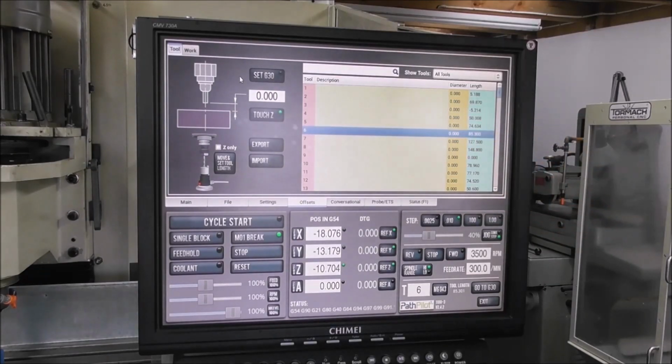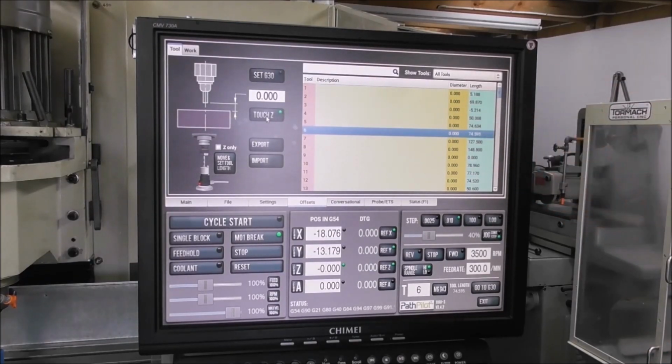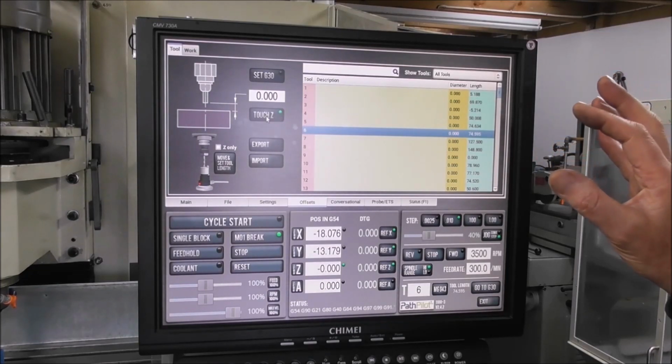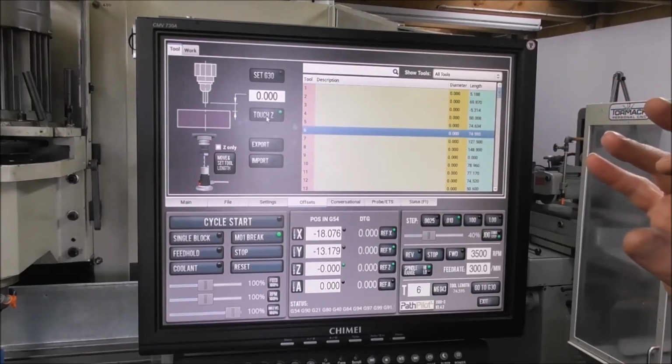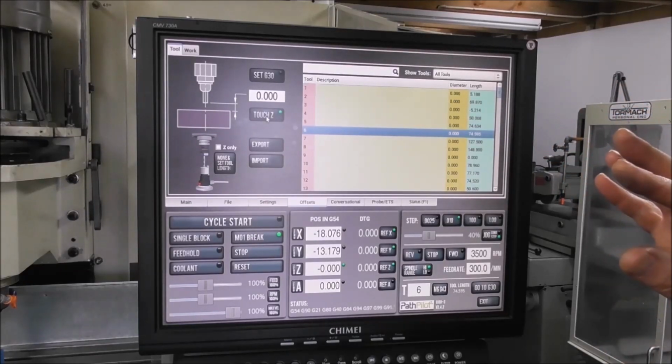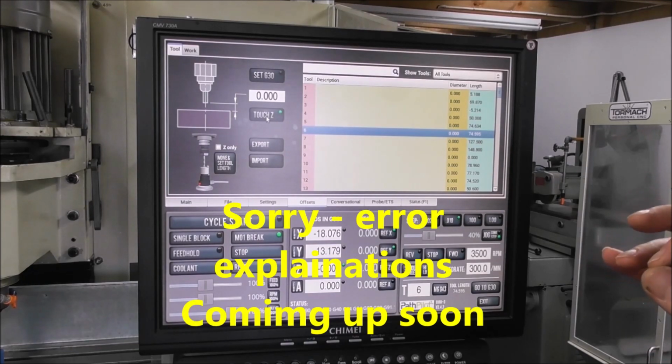Now what was the tool length with the mechanical reading? It was 74.49. So when I touch that off, we'll see whether it's the same via the on machine measuring. Touch that there and we get 74.59. So that's 0.1 of a millimeter error. That's 1/4 error. So you can see that there's quite a big discrepancy between the two different methods. Probably most of the error or the difference will be in the off machine methods of measuring. We already found 2 errors that I discussed, so I would say most of the issue is there.